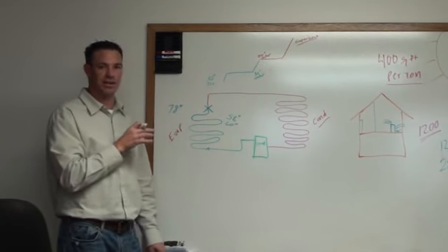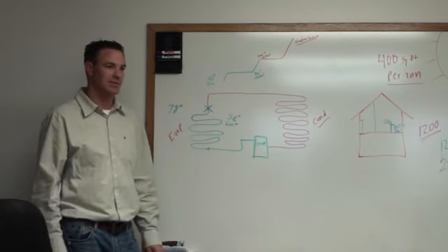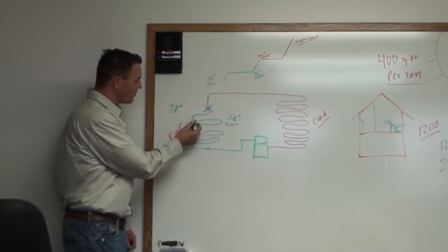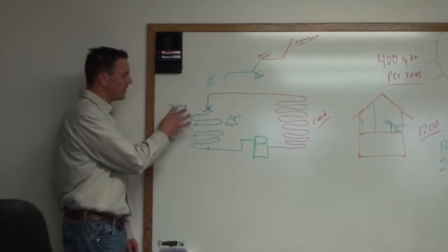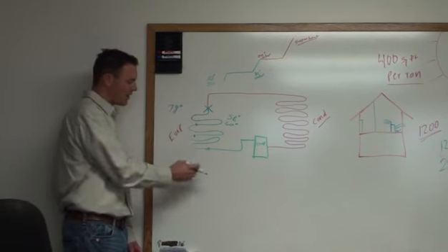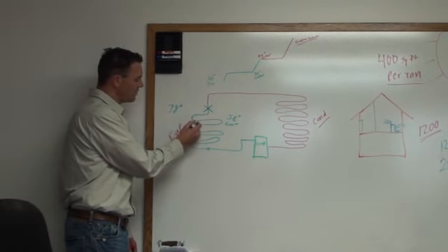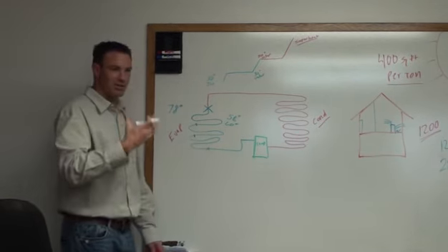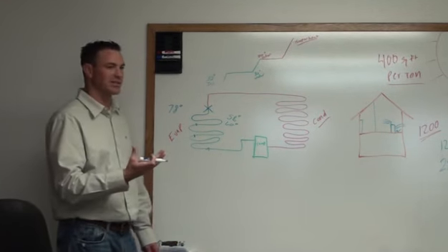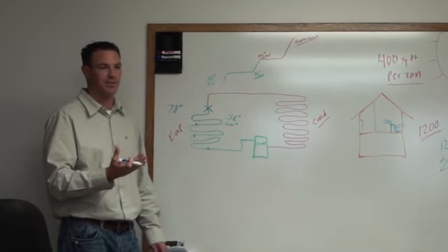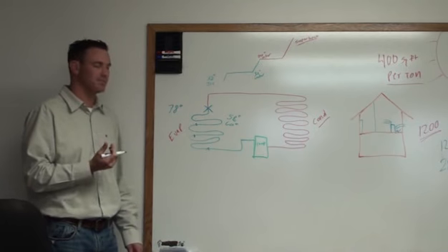For us to get the refrigerant into a vapor form, it has to be boiled off or vaporized or turned into essentially superheat. So from this point right here to this point, you're going to change state from a semi-liquid to 100% vapor, okay? You use this point to this point to absorb additional superheat, and the superheat kind of serves another purpose. It also protects the compressor from pumping liquid refrigerant. The compressor cannot pump liquid refrigerant or it'll ruin the compressor.